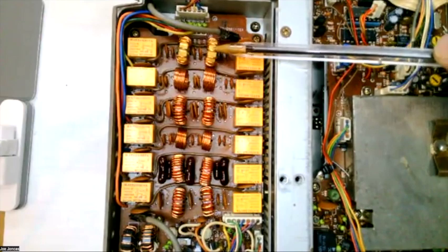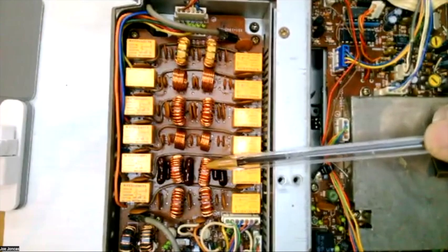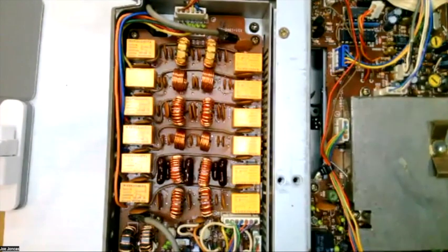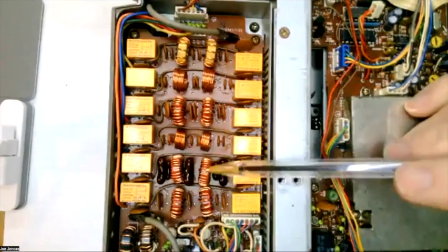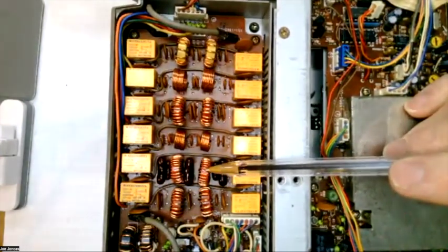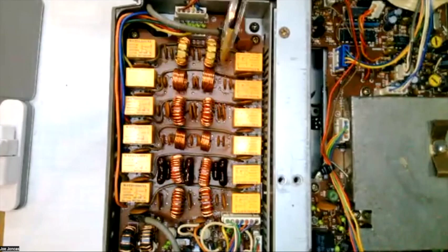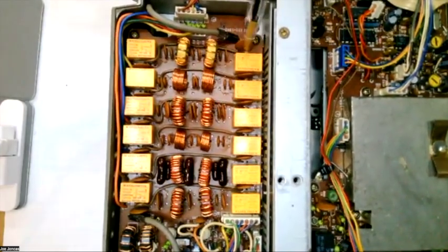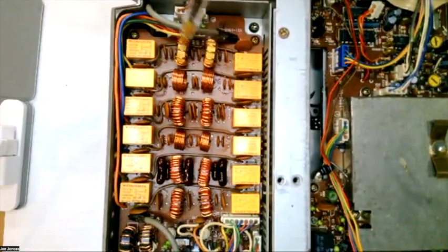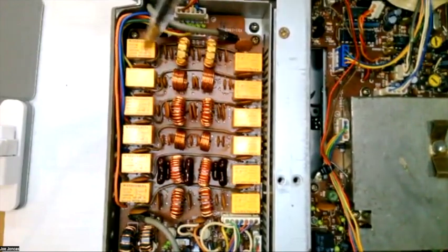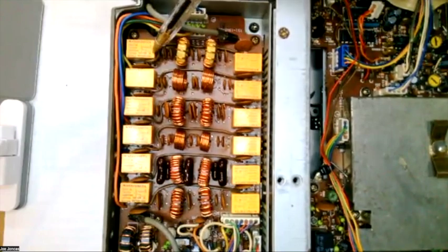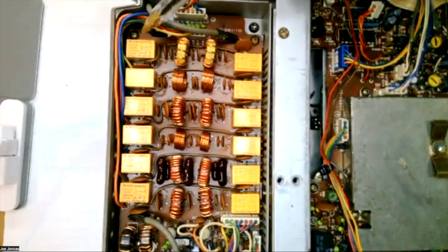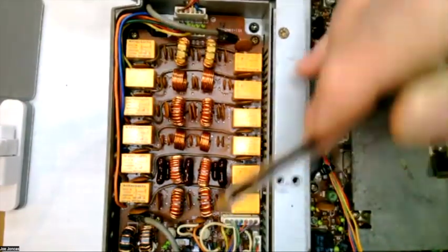This one I think is 20 meters, 40 meters, and 80 meters. And the reason I know is because this has more coil and this will have more inductance. But these ones, you can see the capacitors down here and the coils. And this is a bandpass filter. And this one, I think I said was 20 meters. So it allows 20 meters to go through and not any of the rest.